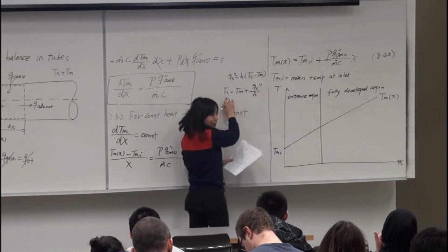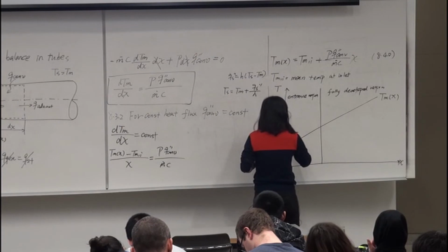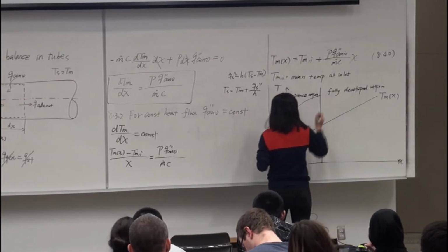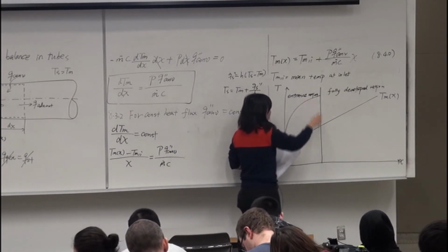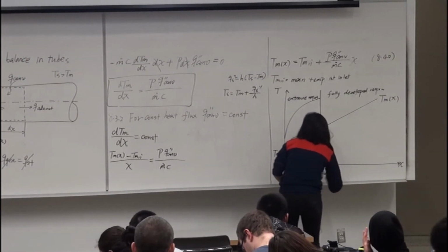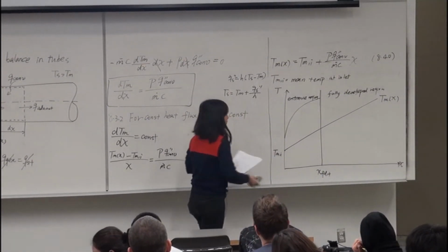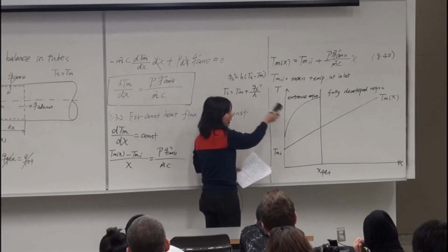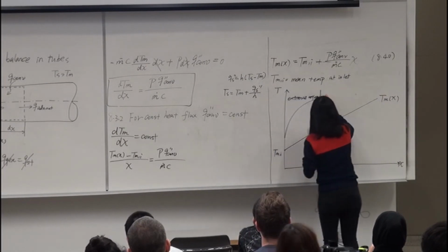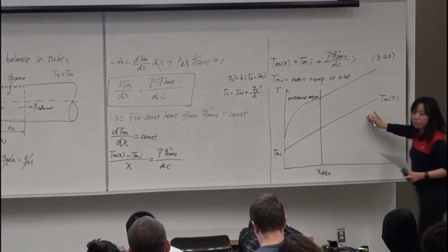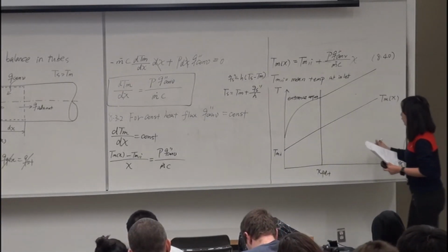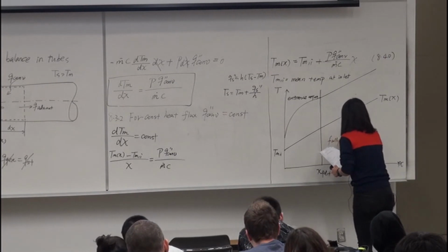Since h decreases while the convective heat flux is constant, T_s keeps growing at the entrance. Something like that. But once we reach our thermal entry length, h remains constant and does not vary anymore. It becomes parallel, because this difference is now constant after we reach the fully developed region.